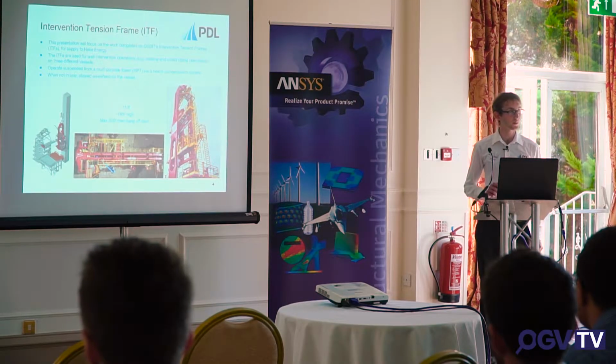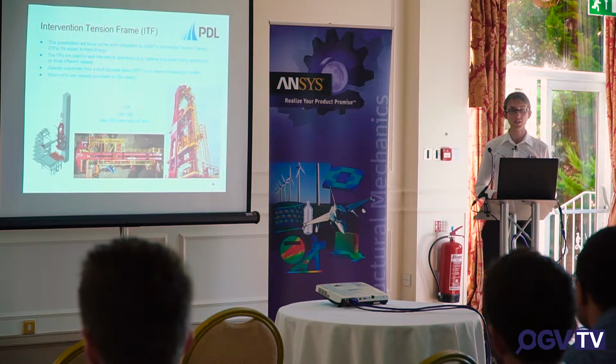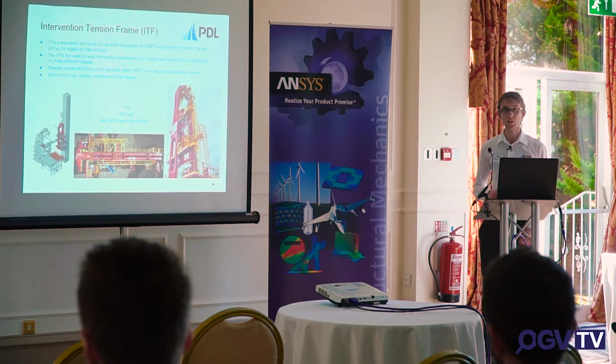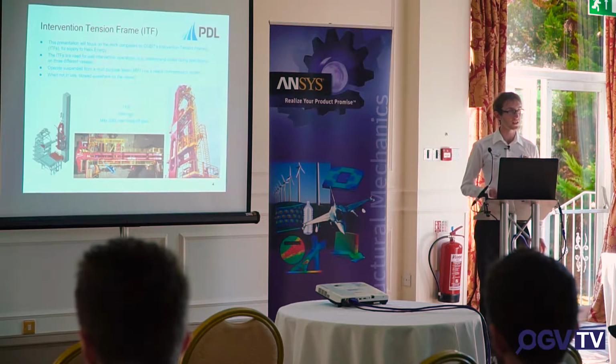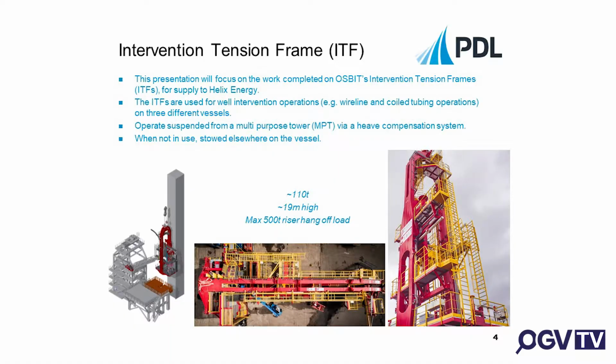So I'm going to concentrate in this presentation on the ITF, or intervention tension frame, to give it its full, slightly tongue-twisting name. The ITF provides a platform for well intervention equipment. When it's in use, it's attached to a multi-purpose tower, or MPT. You imagine a large crane in the middle of the vessel, and you attach this to it, and then the entire thing is heave compensated. So you've got this 110-ton structure, the whole thing heave compensated, and it supports a riser hang-off load of up to 500 tons.